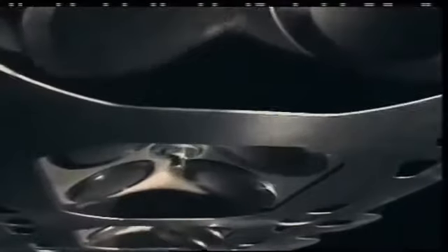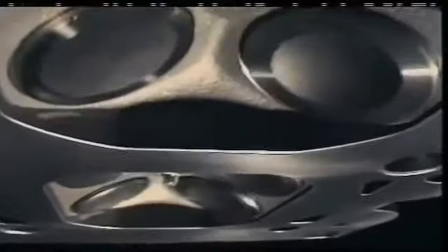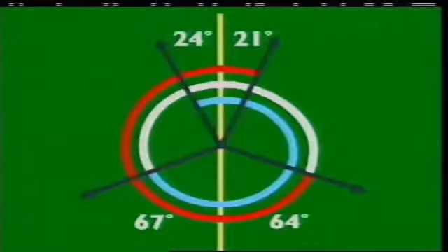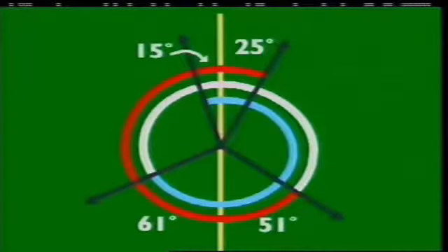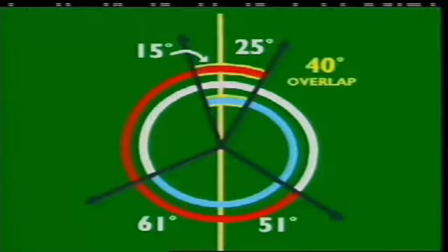Gas flow rate and volumetric efficiency can be improved by using 2 intake valves in each cylinder. The effective port opening is increased and the gas flow rate increases. Changing valve timing also alters the combustion process. Reducing valve overlap reduces the scavenging effect. It also reduces hydrocarbon emission.